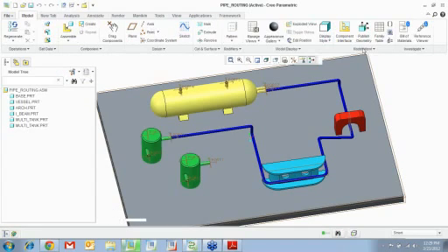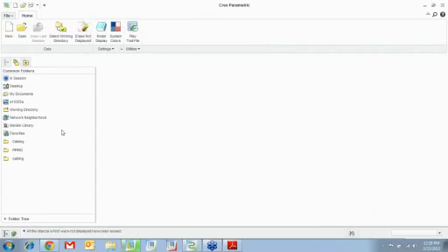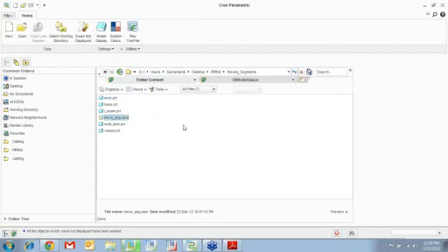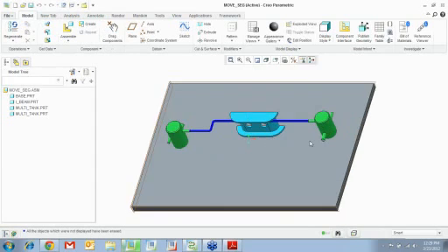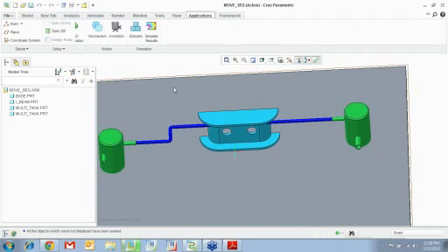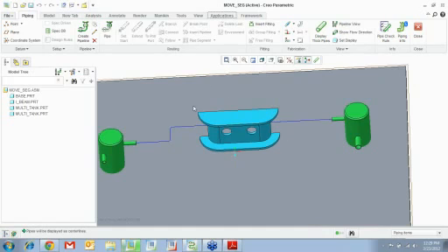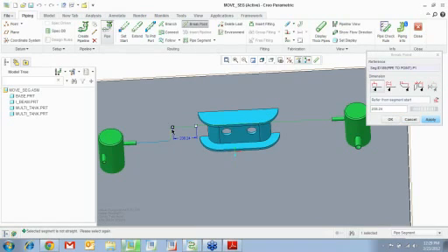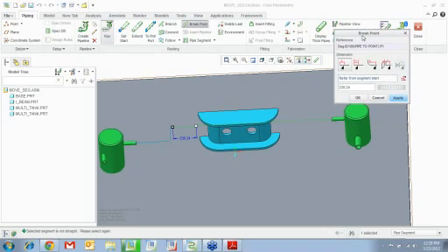Now the next example that we're going to talk about is editing this particular pipe. So here I have a pipeline like this. Get into piping. You want to move the segment. So what you can do is you can say route this particular pipe, insert a breakpoint. So I'm going to insert a breakpoint right there, and you see how I can dimension it, right? I can dimension it by length or by length ratio, distance from, you know, a previous corner, distance from a selected plane. I have different options right here.